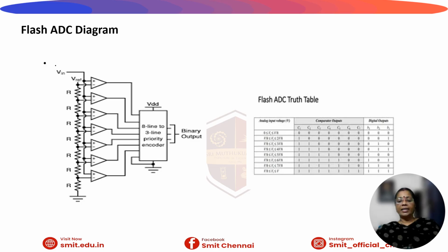Simultaneous comparison is done by feeding the analog input signal into all comparators at the same time. Thus, it performs the parallel operation. If the analog input voltage is higher than the comparator's reference voltage, the output is 1. If it is lower, the output is 0. Because the references are ordered, the output always looks like a mercury thermometer, the sequence of ones at the bottom followed by zeros at the top.